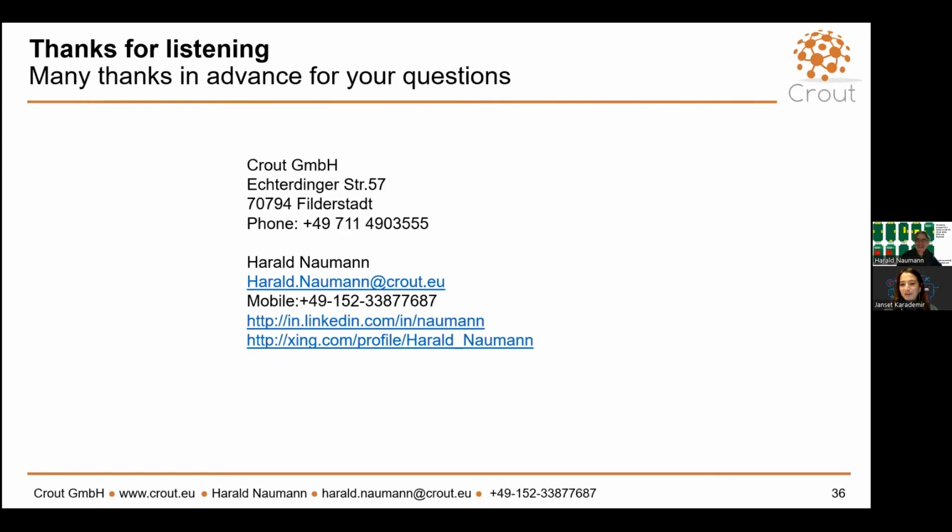Yeah, this is another slide, another session. I have a complete comparison of mesh versus narrowband IoT. I have a mesh network on 868 megahertz by NeoCortex, and the energy consumption in the mesh network is such that I can run a mesh network on 2 AA cells for 7 years, communicating, I think, 240 packages per day. So narrowband IoT and LTE-M will lose.